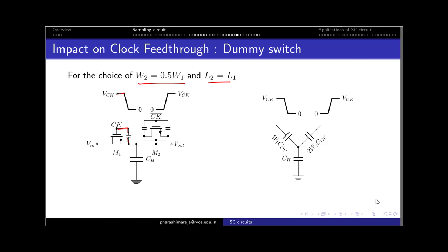Whenever the clock makes a transition from high to low, this creates a negative voltage on this Vout. As I stated before, because there is a negative transition, there is a delta V change that it induces onto this Vout. So Vout is defined as Vin minus delta V due to this negative edge.